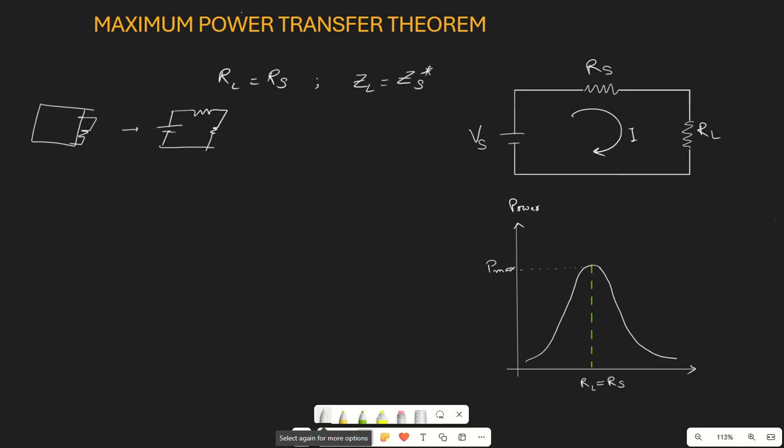The voltage source is given by VTH and the series resistance by RTH, where RTH is the internal resistance of VTH, because we measure both across the same terminals. Since any circuit can be converted into this, maximum power transfer is valid for every circuit, and maximum power will be transferred whenever RL equals RTH. So let's see how this can be proved.